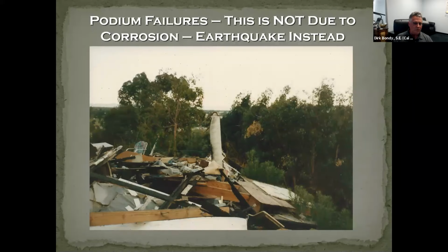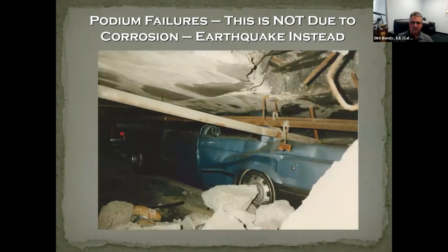By the way, I hope none of you use those delayed connections where you allow a temporary release and slipping of a slab along a seismic system and ask the contractor to come back in later and connect it, because they don't sometimes. And in this particular case, they didn't. And this led to a failure. We never use the temporary releases. We find other ways to do it. That's a different talk. But I want to show you, this is what punching shear failure looks like.